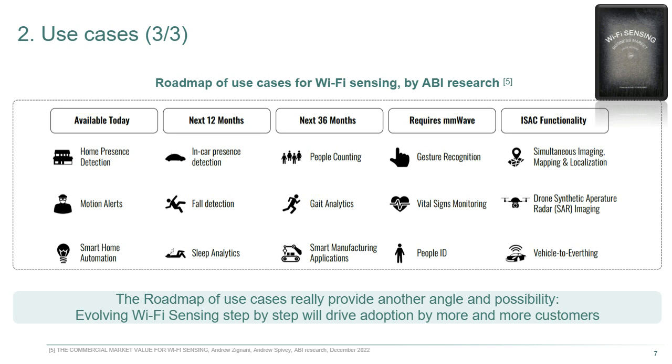This is a good question. Basically, we use Wi-Fi signals, not dedicated sensors, to detect or measure the sensing parameters. Your second question is, if you are using Wi-Fi signals, how do you sense, right? Wi-Fi packets are already designed with parts called, for example, LTF and STF, which are predefined parts. They're not random.